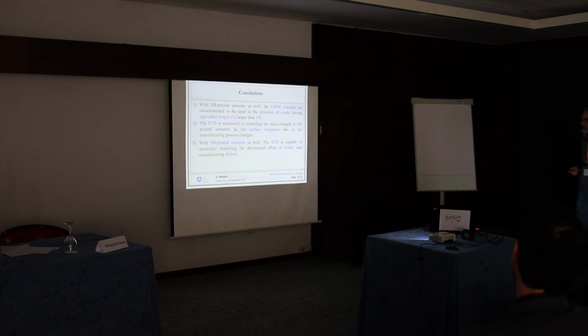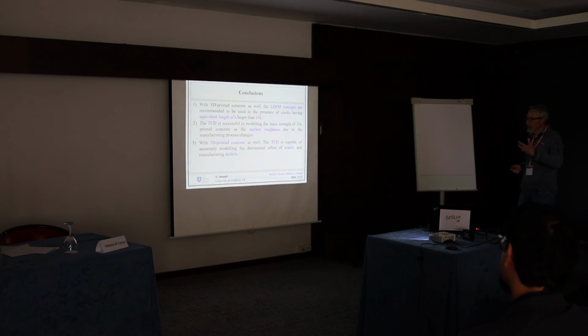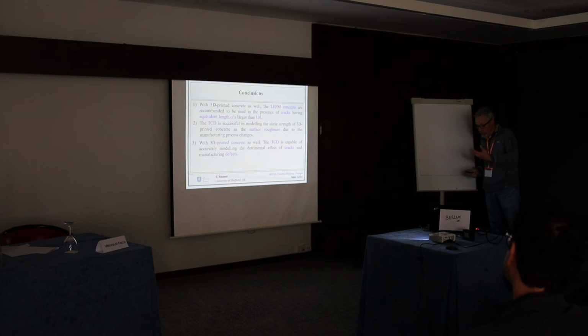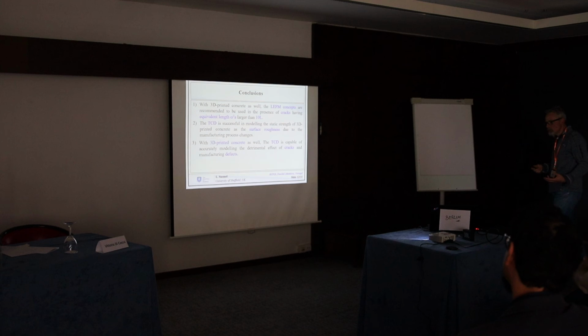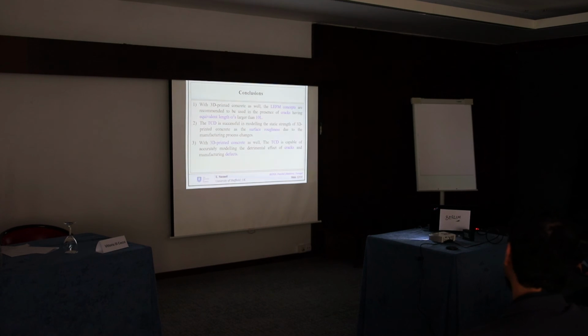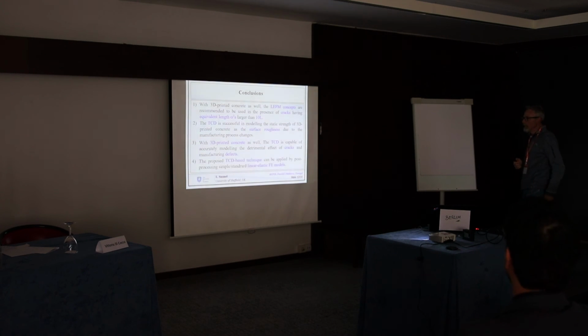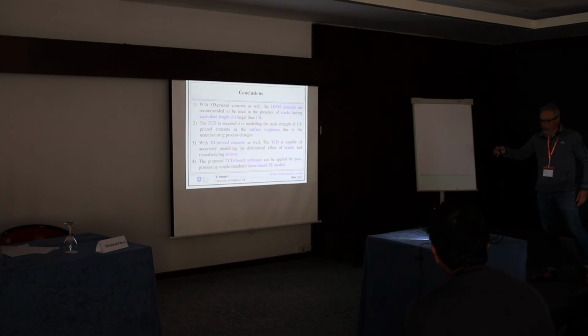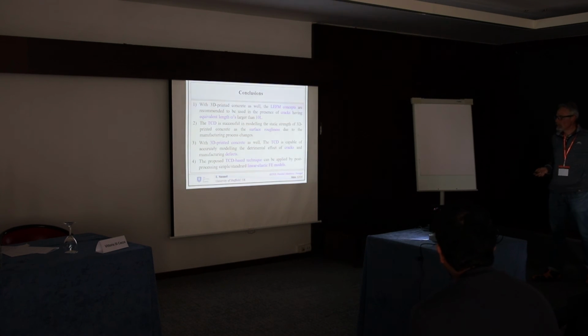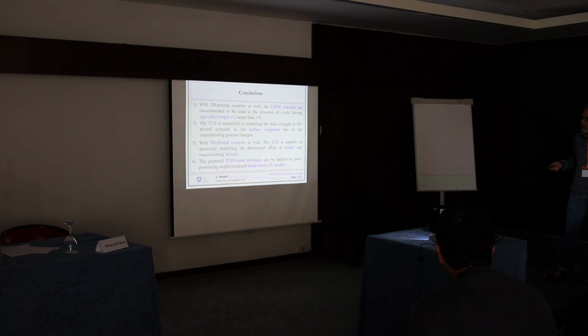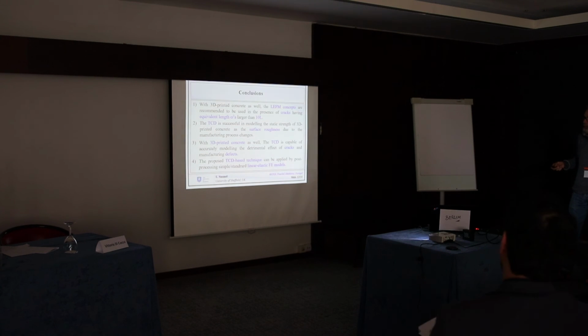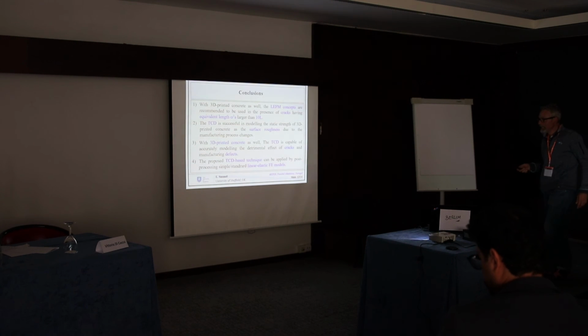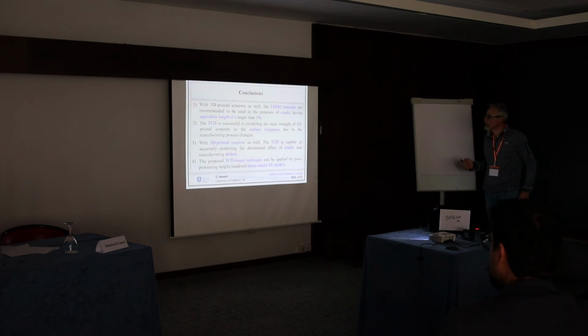You can model the presence of cracks and defects. The cracks or the defects could be due to the manufacturing process, or also due to other problems, for instance, problems you might have during curing. And the good thing is that this simple technique, using standard ingredients, if you like, can be applied by directly post-processing conventional standard linear elastic FE models.